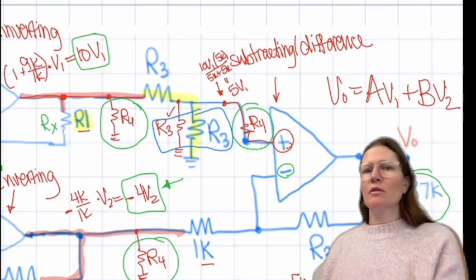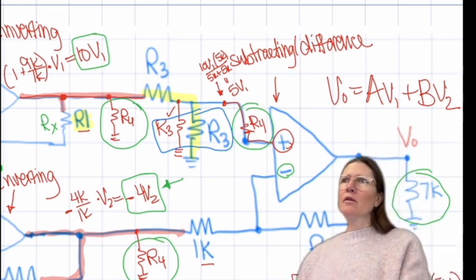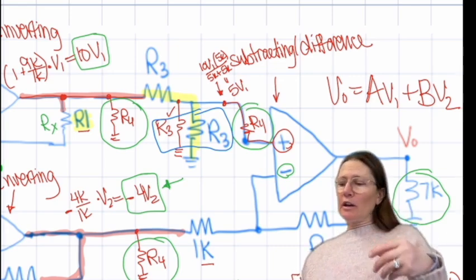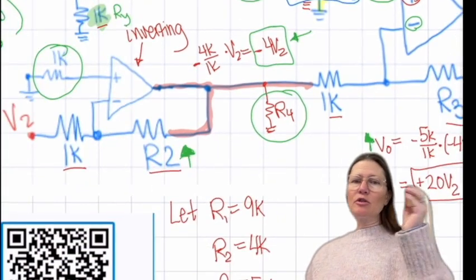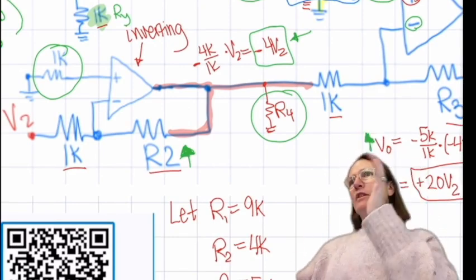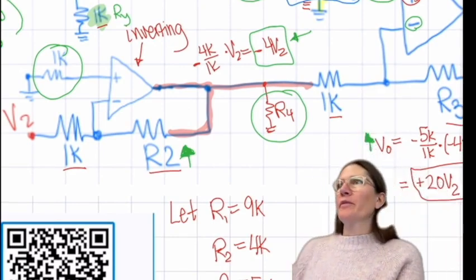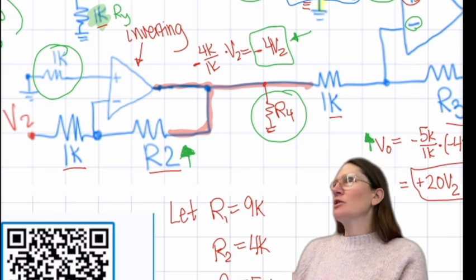So basically, if we have extra resistors that would change the voltage, do we just need to get an equivalent resistance into the simplified circuit that kind of matches the op-amp configuration? Correct. And then, like here, looking at just R2, you already know the equation, so you would look at the effect based on the equation itself. All right, any other questions?